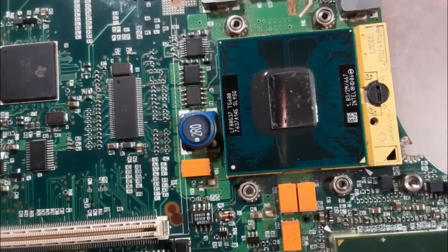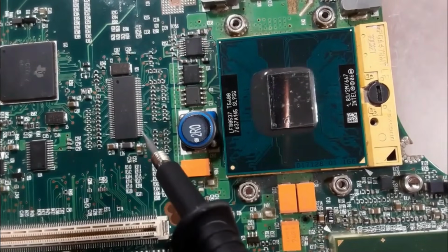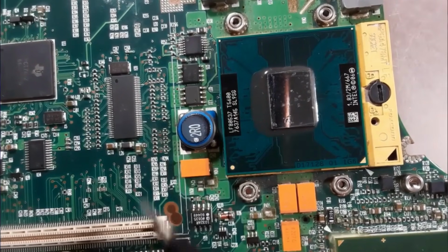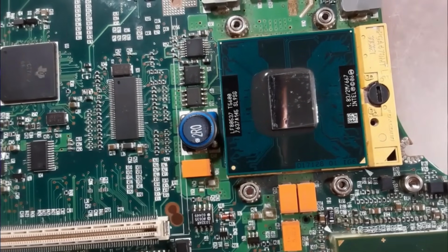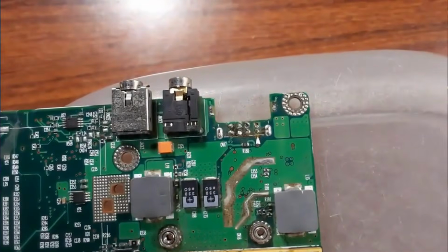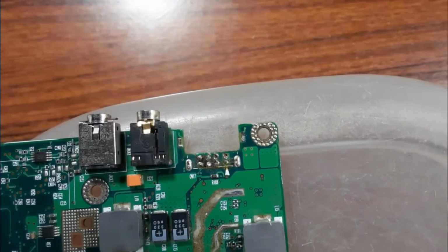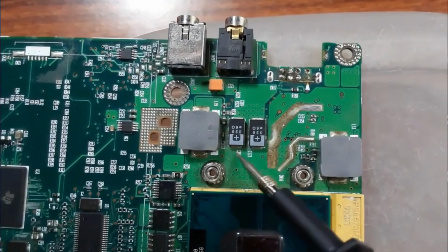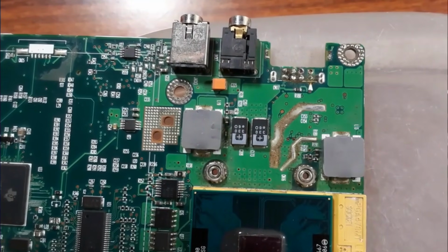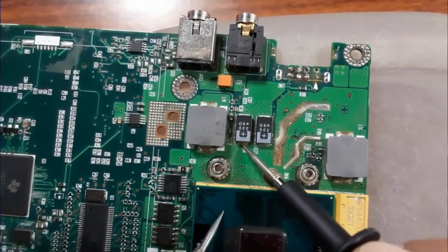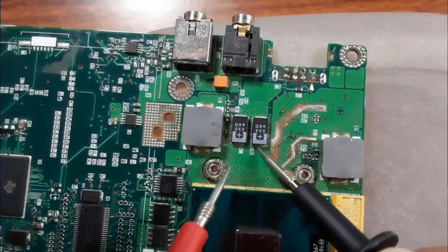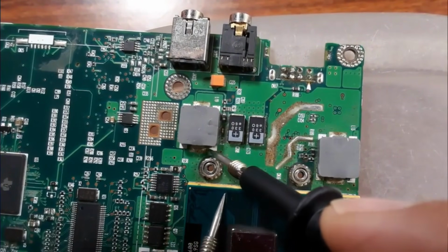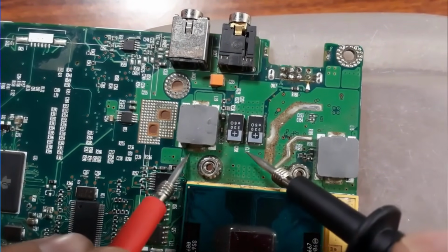So always try, in the ICs that contain pins that are near to each other, to use the extension to take a measurement. Okay? So let's check over here other tanks. As you can see here, for example, these 2 capacitors, this is a chemical capacitor. These 2 capacitors are connected together because here we have the same color, and also this color connects this coil to this capacitor.